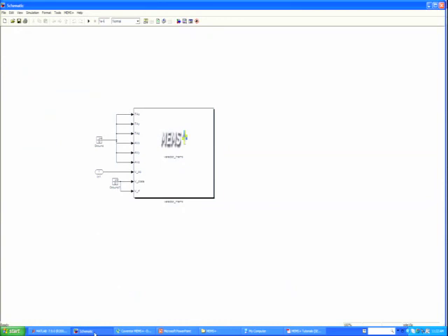Okay. Now it looks fairly simple. We have shown you at least a slide of a more complicated circuit around this, but this is a very simple device, so it's a fairly simple schematic. We've grounded the reference frames because we're going to put a stimulus on it in the next step. We also grounded the voltages, so there's no voltage on this thing at all. Okay, everything is at 0 bias. This is the model we're going to run.